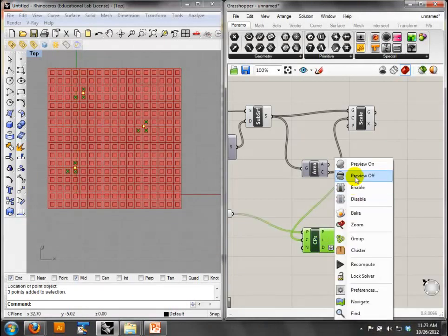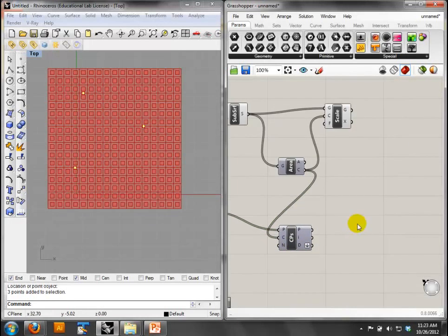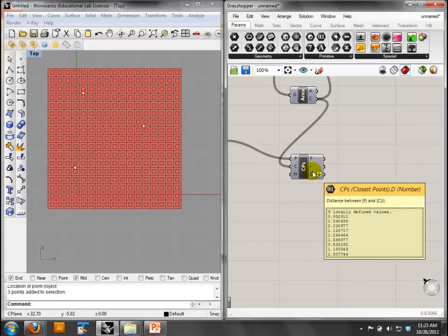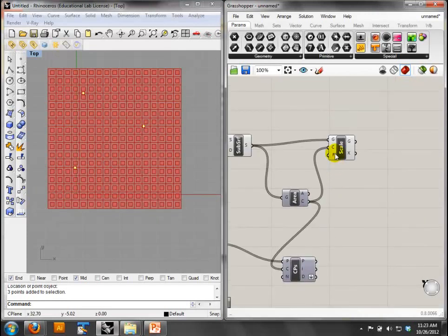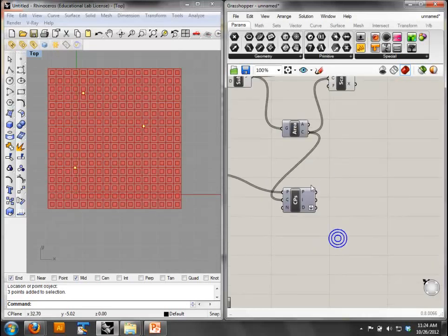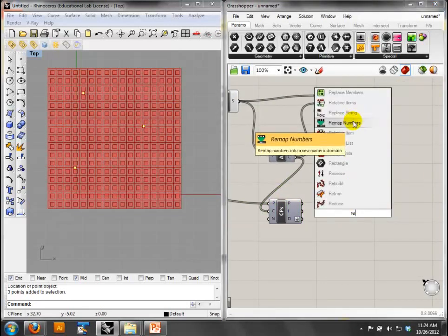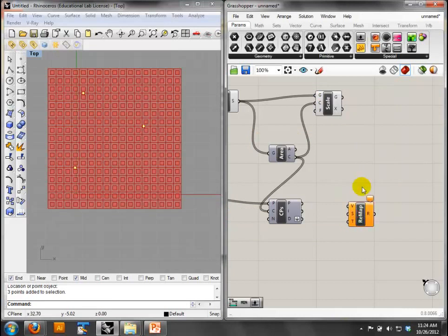Okay, I'm going to go ahead and hide this here. Okay, the other thing that we're going to do, though, so we get a list of values, and there's a pretty wide range in there. Remember that scale takes a scaling factor, and it's some number, so it's basically like multiplying that. So 0.5 is 50%, 2 would be twice the size, right? So we can't just feed raw distances into this thing and expect to get any kind of meaningful output with that, all right? So I'm going to show you another trick. So we talked about closest points. That's a new one. The other one I'm going to talk about is called remapping. And this thing is really excellent.